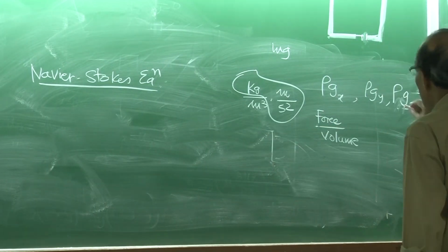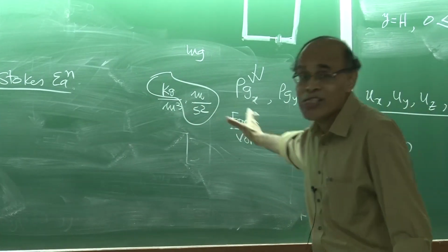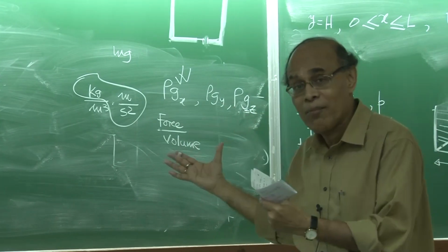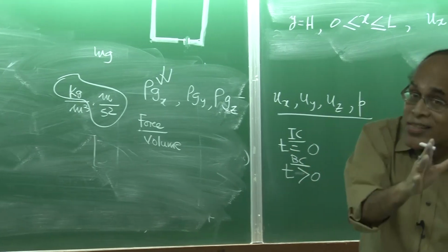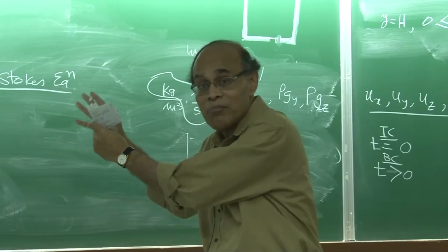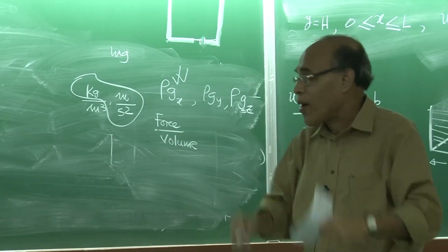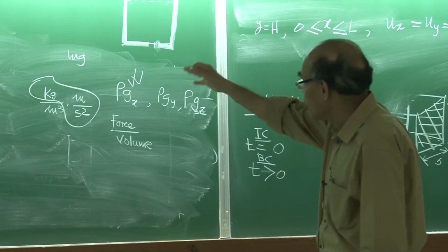Now, if you imagine that I divide all these terms by rho g, if you consider the first equation, the x momentum conservation equation, even though the equations are not on the board, I would like you to visualize them. The moment I say x momentum balance equation, you should immediately realize that I am talking about one unsteady term, 3 convection terms equal to the pressure gradient term plus 3 diffusion terms and the gravity force term. That should immediately appear in your mind.